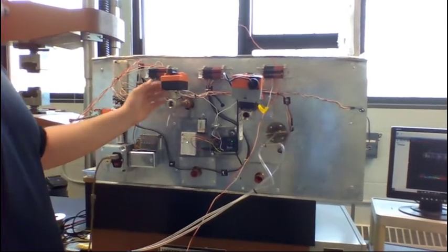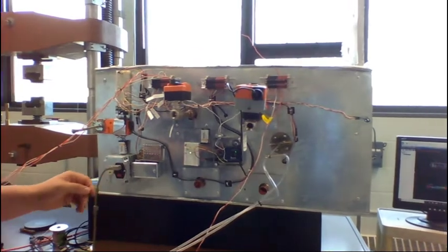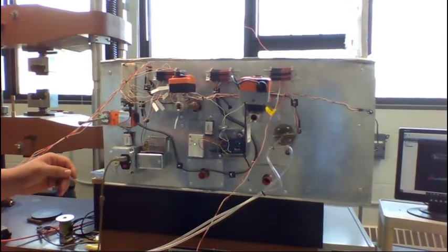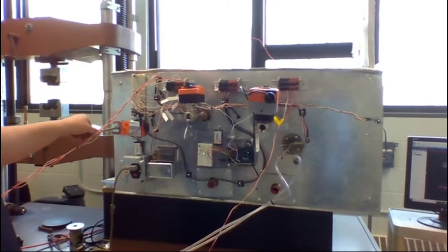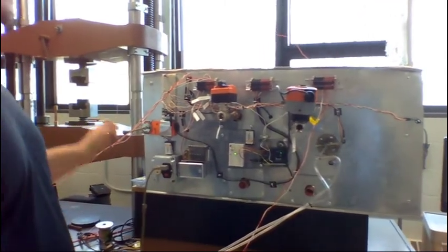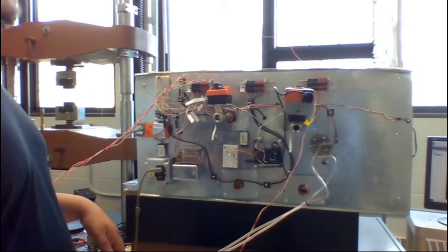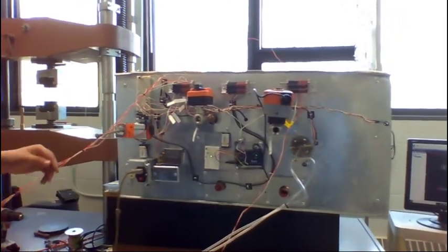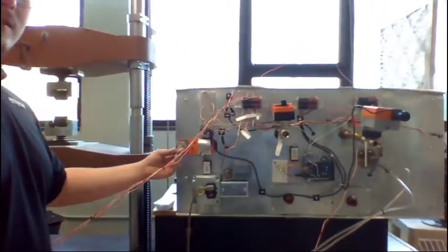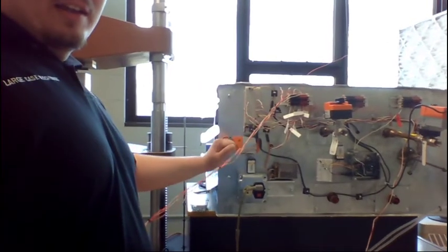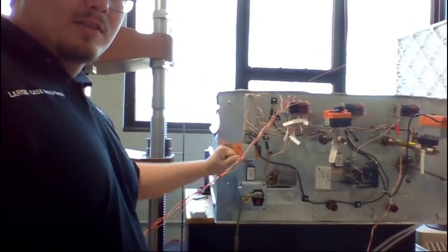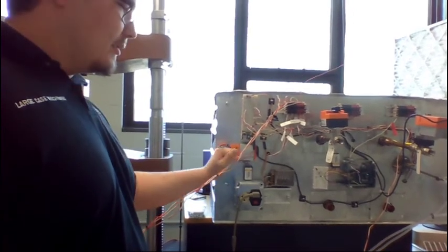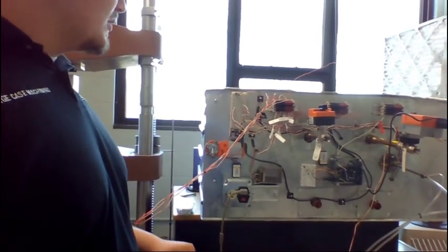The Belimo valves, we're very fortunate to have Professor Weegen, who knew a little bit about this, and told us that these were servo motors, which actually completely saved us because we were wondering how we could actuate these, because they were just known as Belimo valves. Over here we have the damper actuator. By adjusting the Belimo valve, we can adjust the position of these, thus turning this unit into a VAV box, variable air volume, also known as.